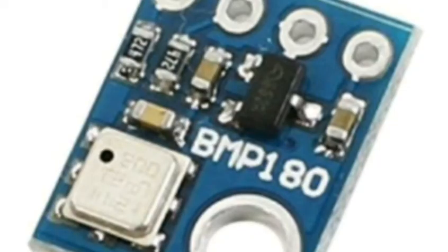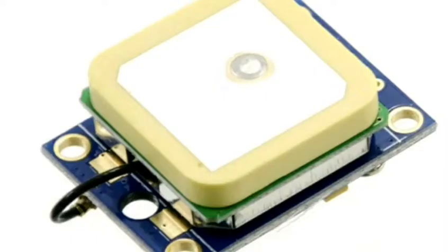We use an external barometer to gain more accuracy, and if the main sensor malfunctions, it can be connected to the autopilot using the I2C interface. For the GPS module, we use one with strong satellite searching capability, the u-blox Neo 6M, which gives location information to the ground control station by connecting it to the autopilot.